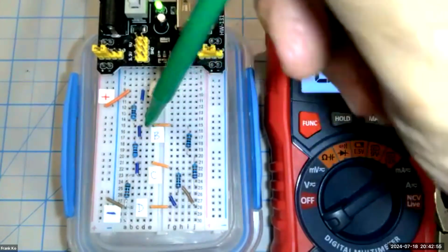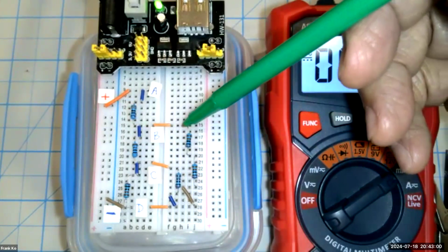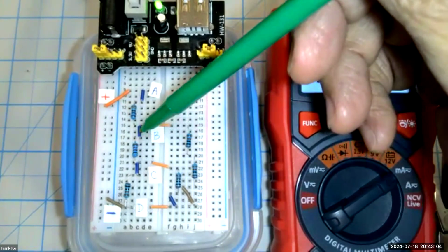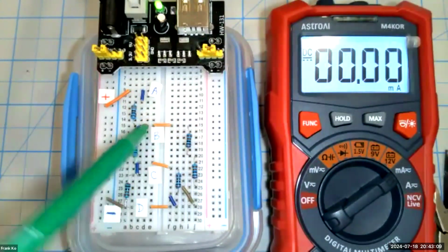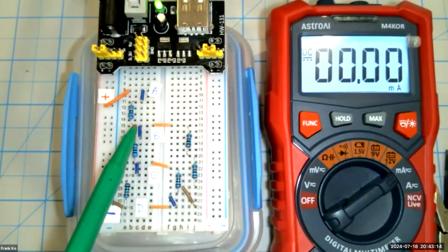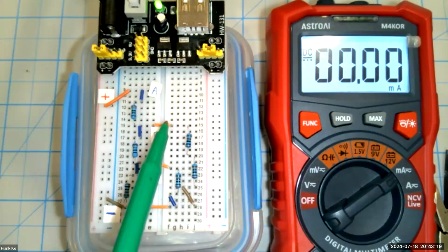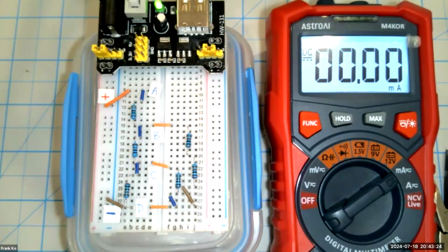So what happens with nodal analysis at point B? The 1 milliamp, which was required as part of the design, flows into node B on this side, plus the 2 milliamps we just measured flowing up into node B. Nodal analysis says these two inbound currents must combine into one outbound current, which must be the sum of the two. So 1 milliamp plus 2 milliamps, we should expect to see 3 milliamps through here. We calculated it. Now we're just going to measure it and confirm that the board is built properly to match our calculations.